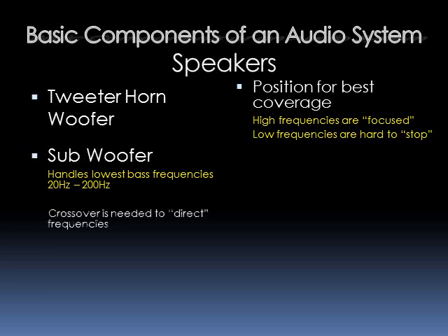A crossover is needed to direct the frequencies. These are built into the speakers so that the tweeter horn, which wants to send out sound waves that are an inch to a half inch in width, is not trying to send out something that is 10 feet in length, as in what would be going to a subwoofer. So the crossover tells what frequencies to go to which speaker so that it can reproduce what it needs to reproduce.